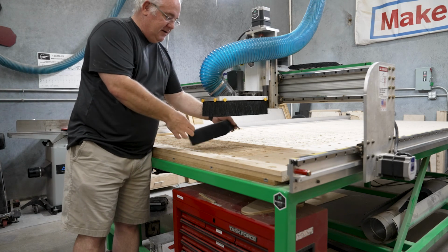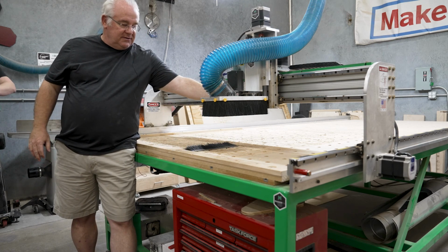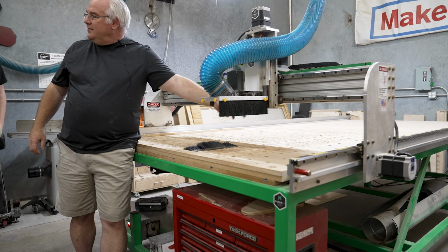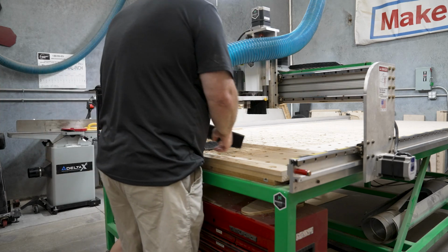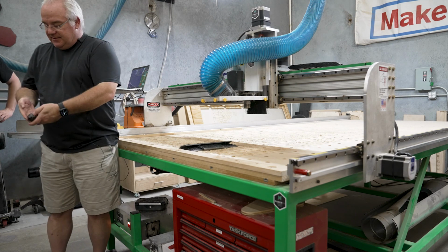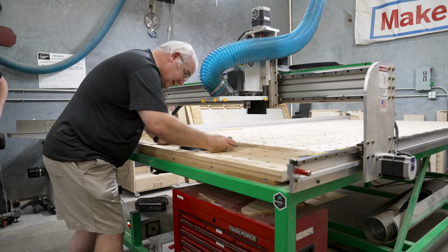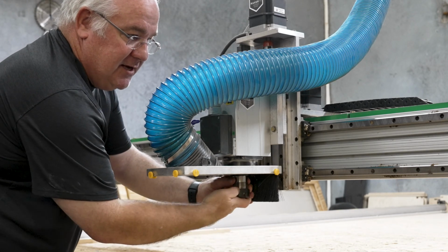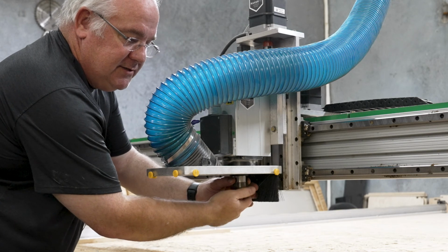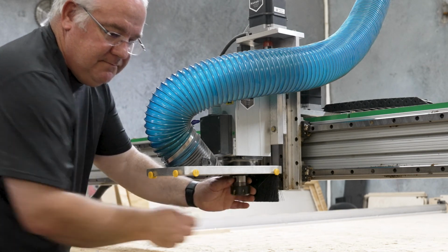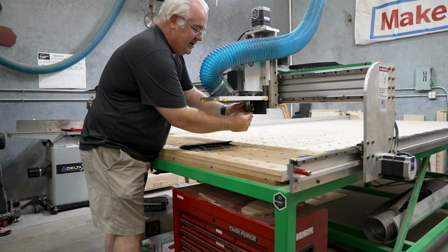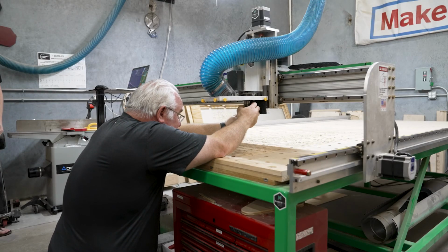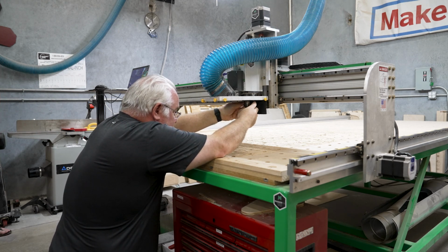The dust shoes, there are 4 of them. There are 2 screws that you have to just loosen for them to come down. You don't ever have to worry about removing the back shoe, but you'll likely want to remove the 3 dust shoes as you do this. We talked about the nut and the collets. I'm going to go ahead and hold the spindle itself with one hand and spin this on, and just move it so that it's hand tightened, so I can actually get that bit pushed up in there, and if not, you kind of push it up and tighten it a little bit so that it does stay.